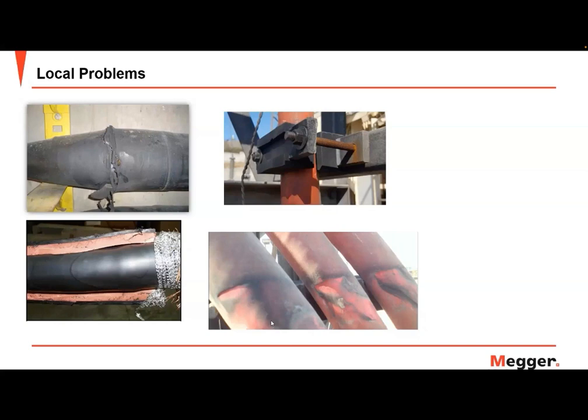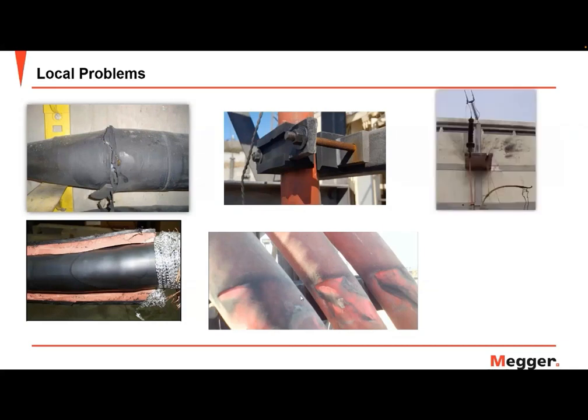And similar to the bend radius, what that's going to do is it can affect the electrical field distribution at that point, and again is a prime point to have some partial discharges or other defects taking place. And that's going to be kind of in the main insulation, obviously, between any of your splices or terminations there.